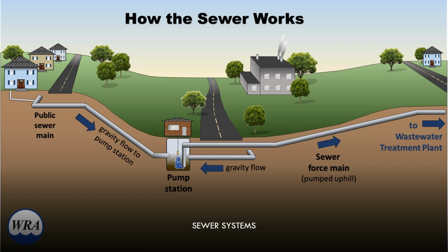and this is going to explain essentially how sewer systems work. Sewer systems are vitally essential to modern plumbing, and every single time you flush a toilet or you use your sink or you take a shower, you are creating liquid waste that contains deadly bacteria and has to be transported and treated. And in ideal conditions, a sewer system will flow downhill through a sewer main line using gravity, and it will travel to a sewage treatment plant.